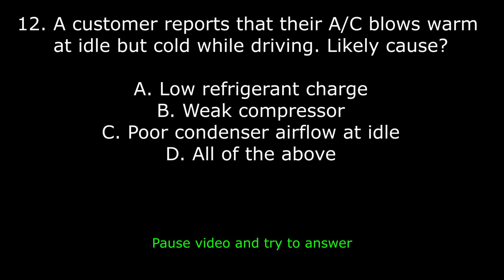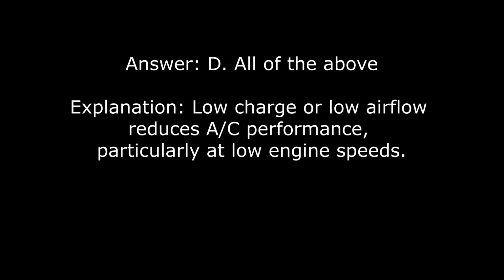12. A customer reports that their AC blows warm at idle, but cold while driving. Likely cause: A. Low refrigerant charge. B. Weak compressor. C. Poor condenser airflow at idle. D. All of the above. The answer is D. All of the above. Explanation: low charge or low airflow reduces AC performance, particularly at low engine speeds.